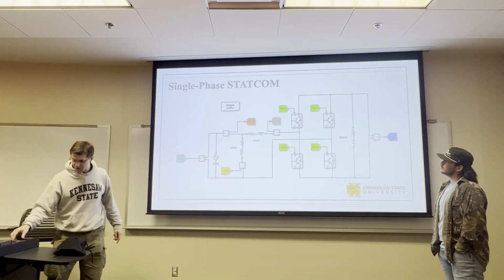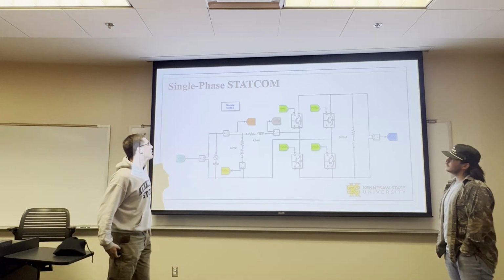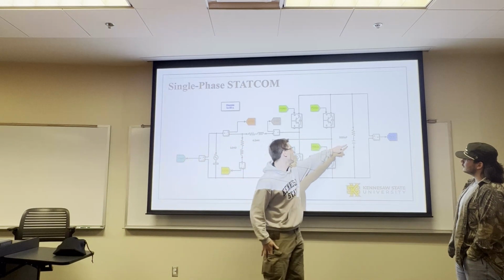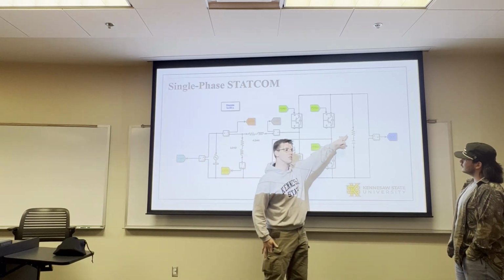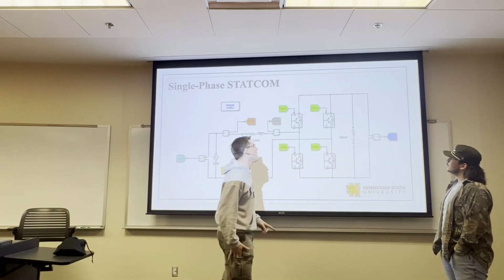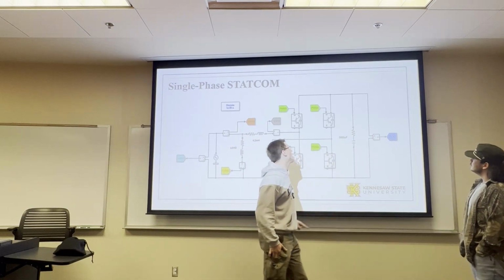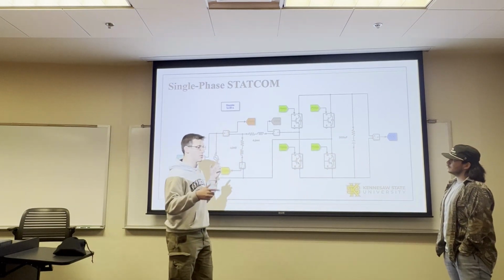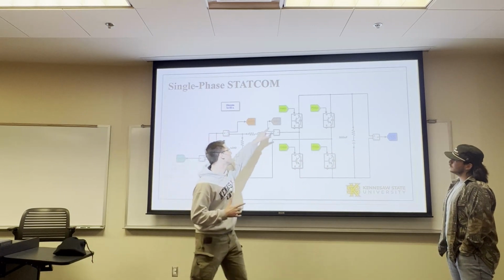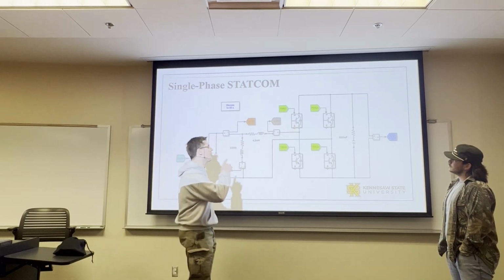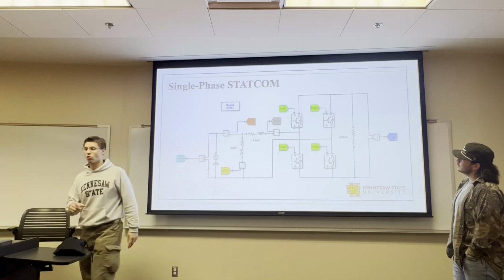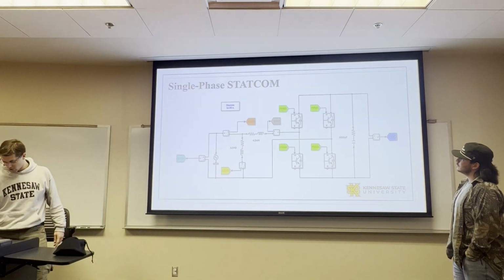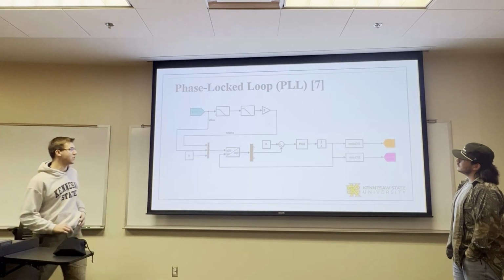Now, so here's the single phase STATCOM. Basically, this is controlled by having a shunt capacitor. This just models the internal resistance and is measured, and from this measurement and the measurement of the grid is how you compute those to get your pulse width modulation, which control each of the electronics of the STATCOM rather than of the grid. Now you've got your phase lock loop.